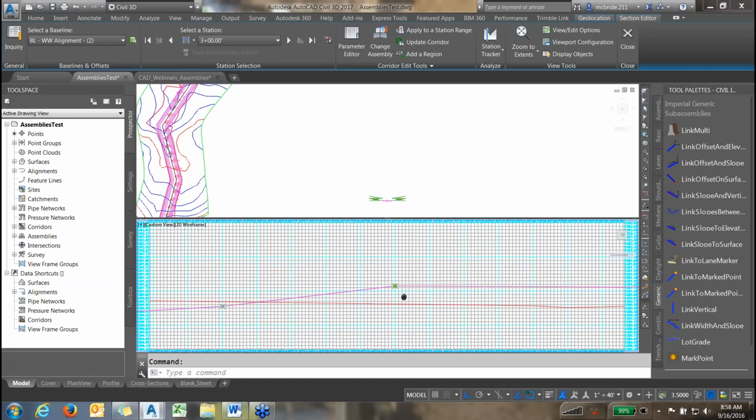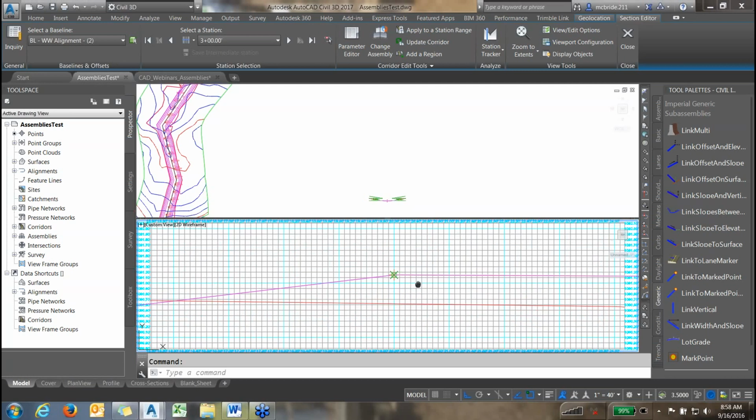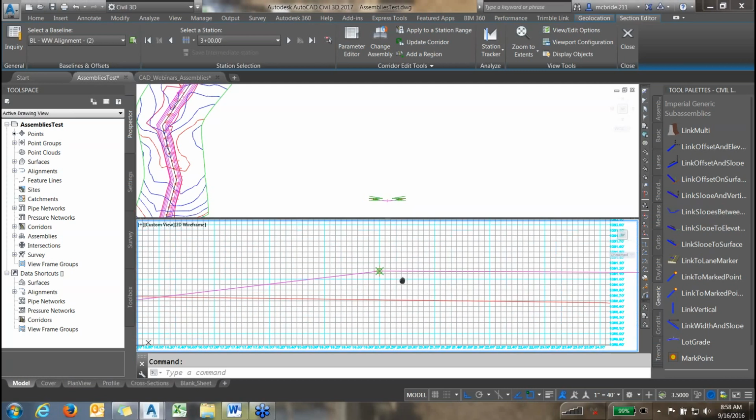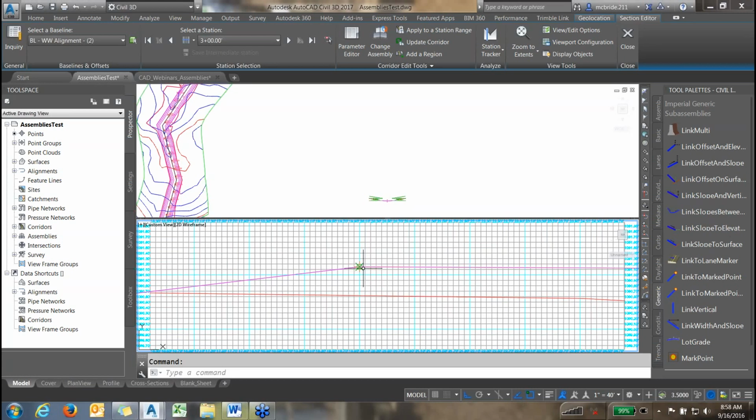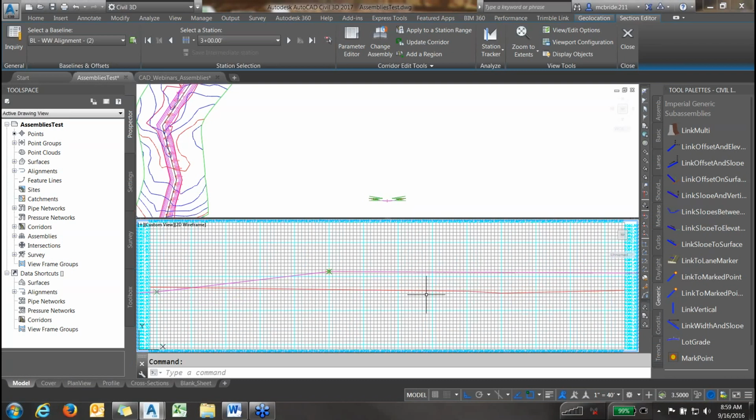Okay, so I'm trying to zoom in here. All right, so it's saying that I'm above the current ground, and so I have to fill to get back to ground. Now, in the case of a grass waterway, I could have done a 6-to-1 slope, which would have taken this point and come down to somewhere right around here, which is fine. But if your ground tends to go up the further out you go, you may not want to have that much of a slope. So this 200-to-1 just gives me a flat slope. It's virtually a flat slope. So you're going up and you're building a flat area of fill until you meet the existing ground.